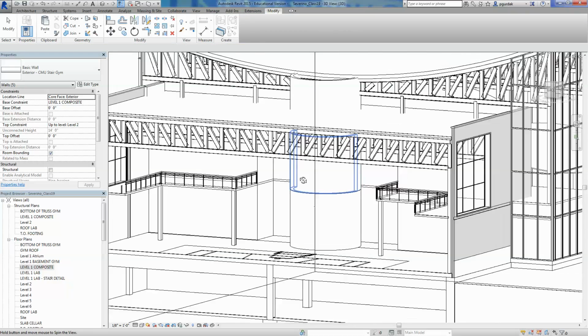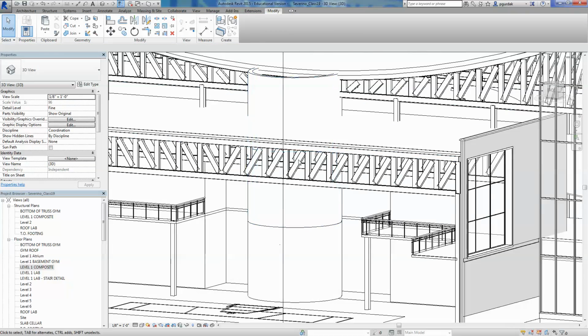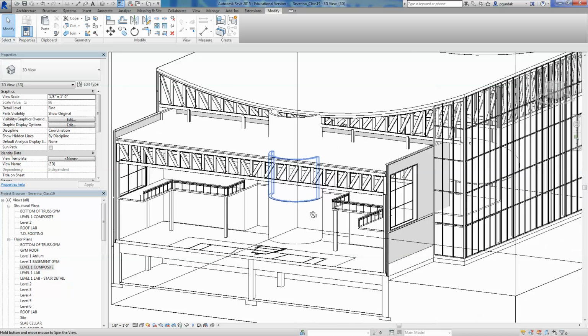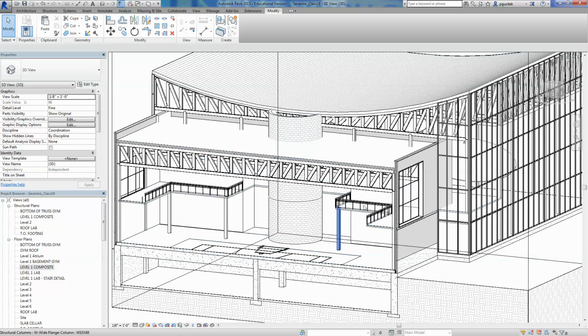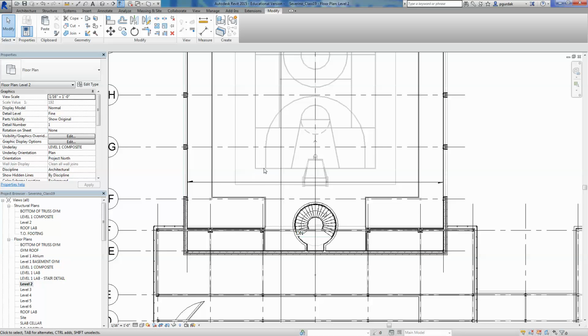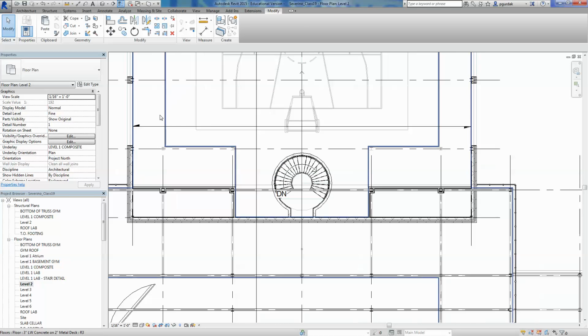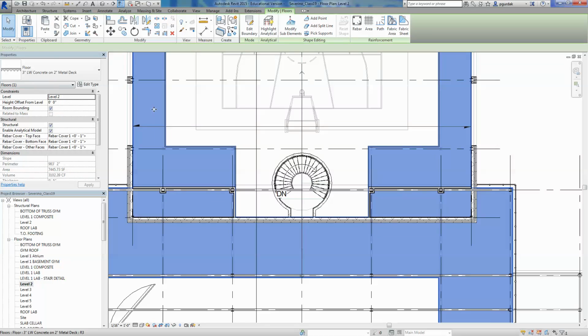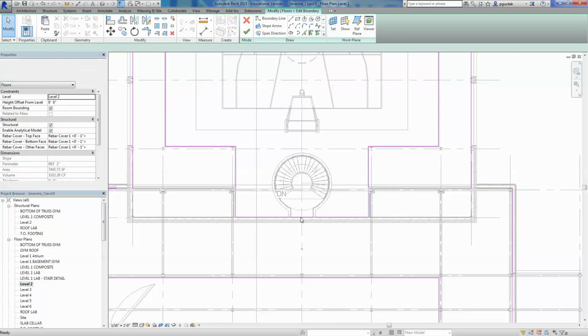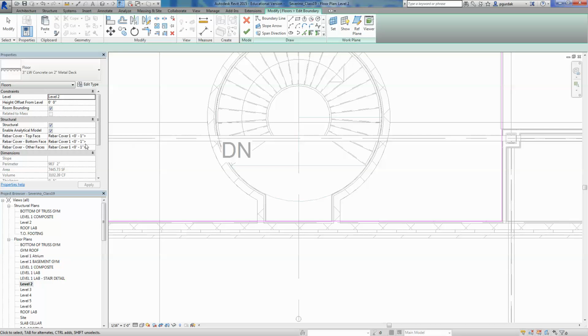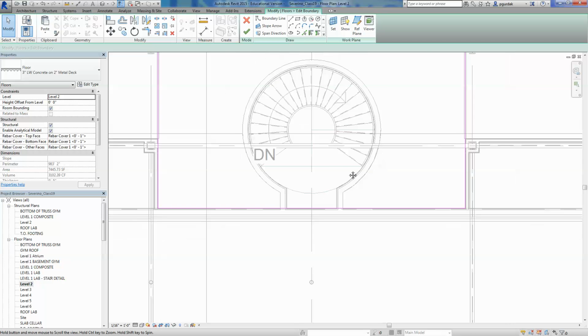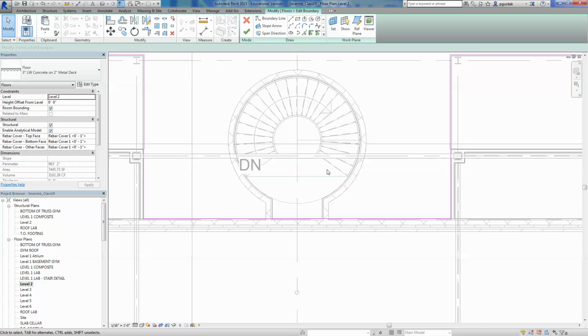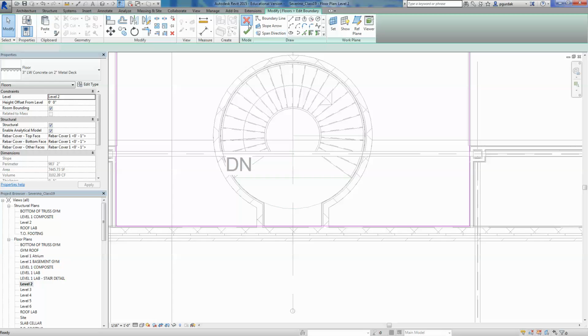And I'm not going to attach to the bottom yet, because I'm going to use this same stair for the atrium. So I will do that. I will copy the whole thing and then I will attach it to the floor. But first of all, I'm going to go to level 2 because I have to change the flooring. Okay, remember that if this is the floor, we need to edit the boundary so we can adapt to the section of the stair. No?